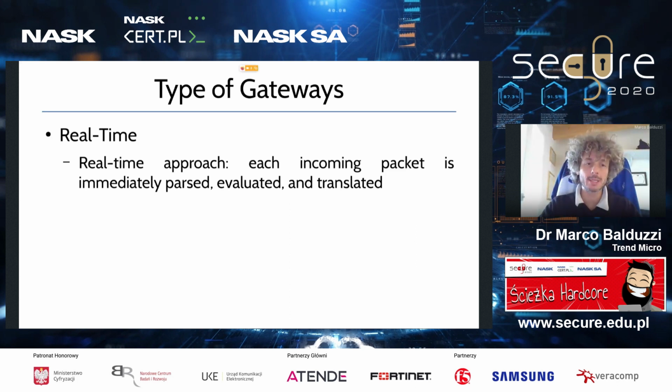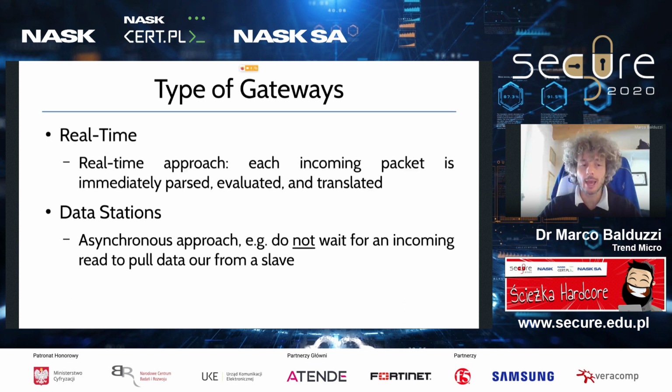And those that are a bit more complex, that use something like an internal caching mechanism for doing an asynchronous translation. I'm going into detail more about this second category of gateways that are called data stations. But what you can think, basically to summarize what they do, they do not wait for a read request. For example, you have a master that wants to read some data out of a sensor. What the master does is trigger a read request for the sensor.